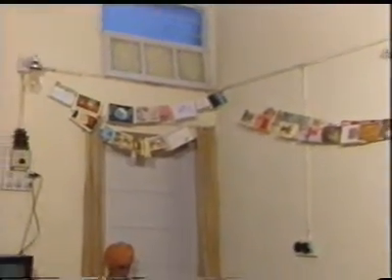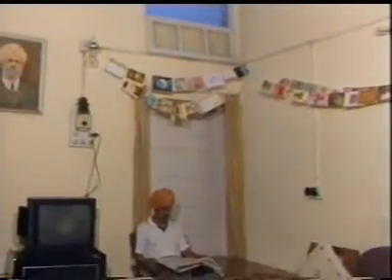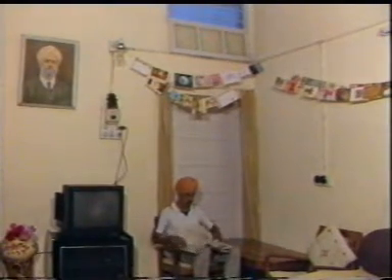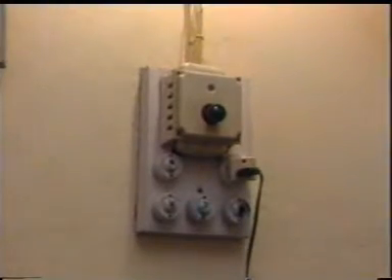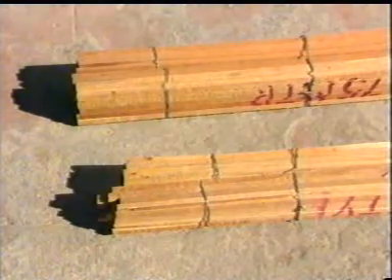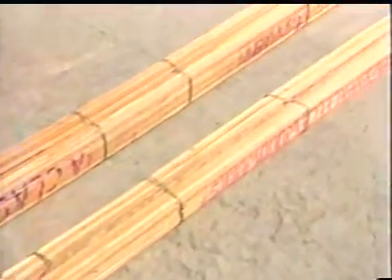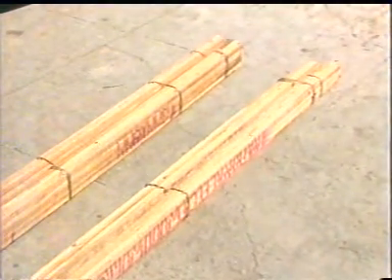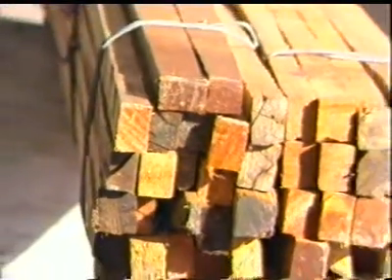The batten wiring is very simple and economical. In this, the sheathed PVC cables run on well-seasoned and varnished teakwood battens. The wooden battens are 10 mm thick and of variable width. The width of battens used will depend on the number of wires to be run on them.